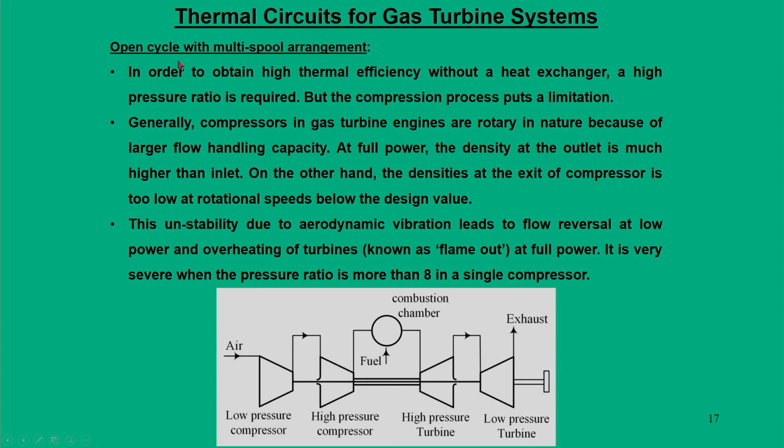There is another concept called a multi-spool arrangement. In some situations we do not want ancillary components like an intercooler, reheater or something like that, but still we require a high compression ratio. In that situation we use a multi-spool arrangement.